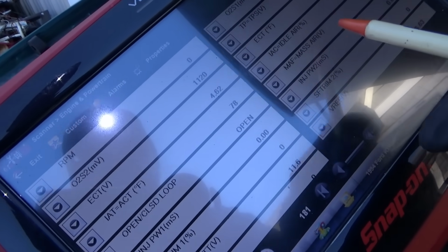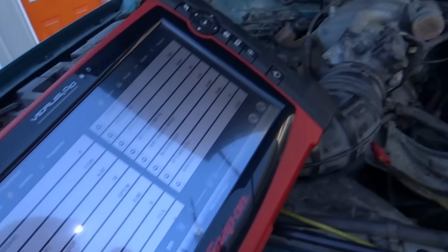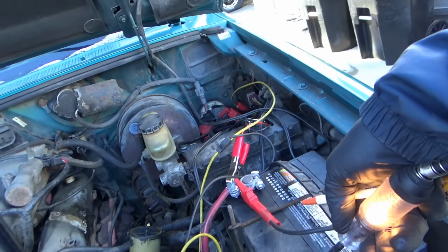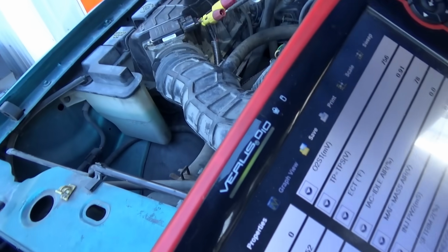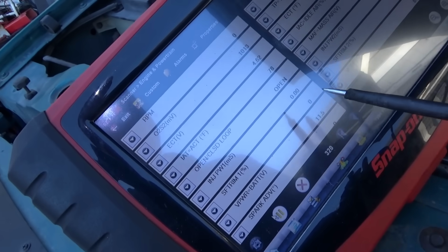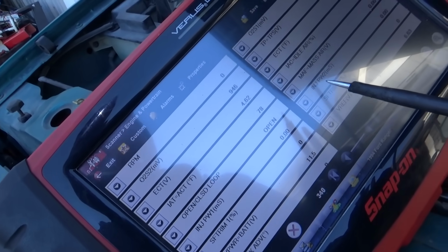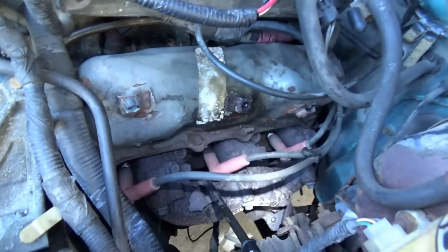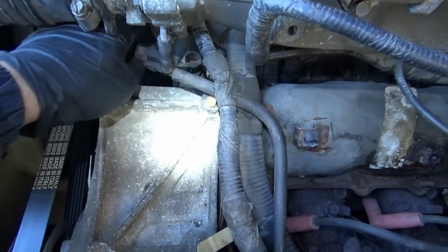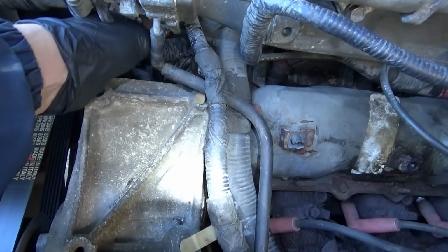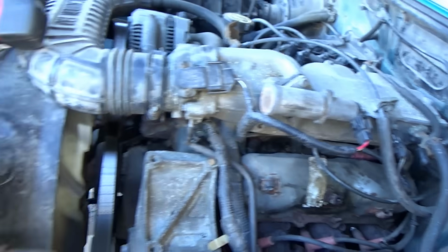So my question is, mass airflow voltage, can we pull that up or down with the test light? We go to battery positive again. That's going to be this wire right here. Mass air, see, it's 0.00. It's not changing on scan data. Now we can check the oxygen sensors, I guess, but can we trust the scan data on these old things? Sometimes that's a variable. We saw one up to 5 volts with the test light, but not when it's just normal operation on the mass airflow.